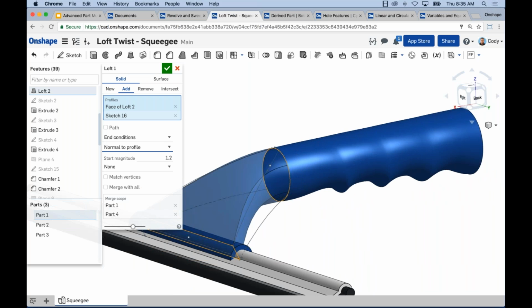All right, so could you have mirrored the guidelines? No, you couldn't have. Those are created on 2 different planes. You can copy and paste the guides, but you could not mirror them. They're on 2 different planes. Could the guidelines be mirrored about a plane? Same question. What I would do in that situation is create 2 guides, create half of the loft, and then mirror the whole loft across. That would be an easy way to ensure I have a symmetric transition.